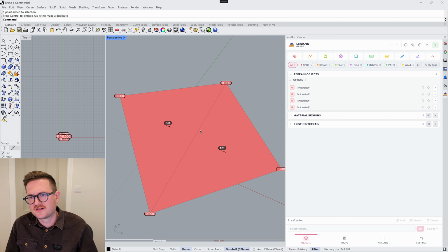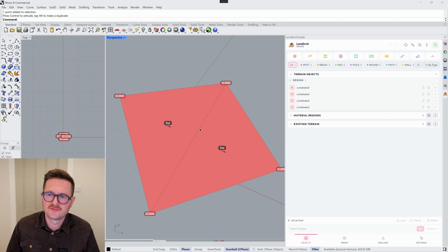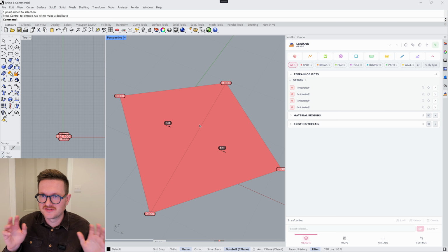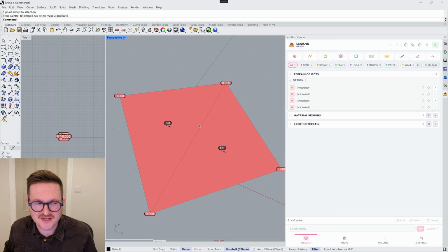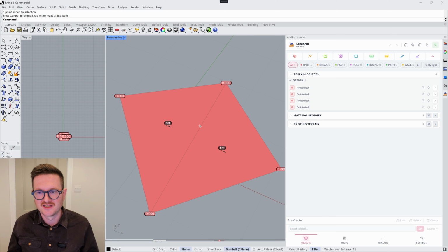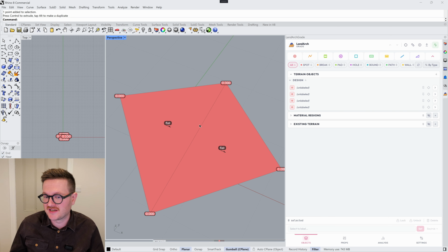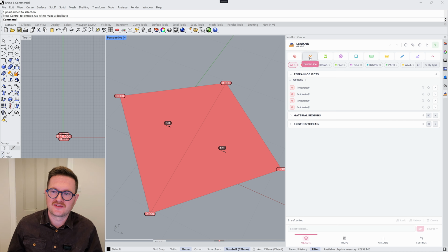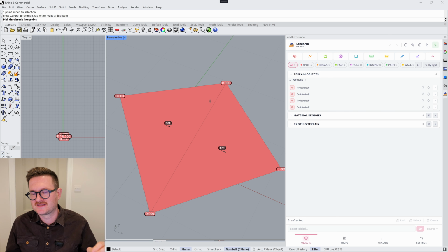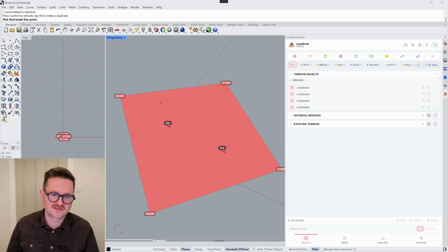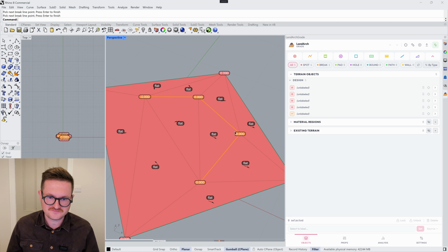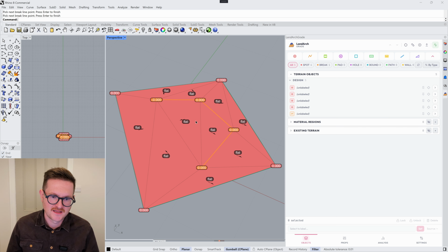What I'm going to introduce now is called break lines. Spot heights and break lines are the fundamental tools of surveying, right? And we're co-opting them as a method of designing terrain. What a break line does is it's essentially the same as a spot height, except it's chained together, right? So when we add that break line to the document, you can see it's a line. And when we add it, you can see that it has broken up this mesh along this break line.